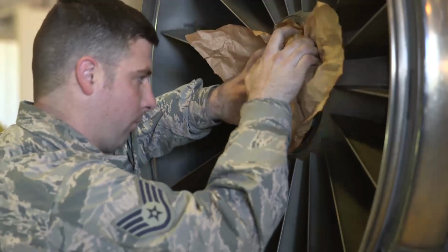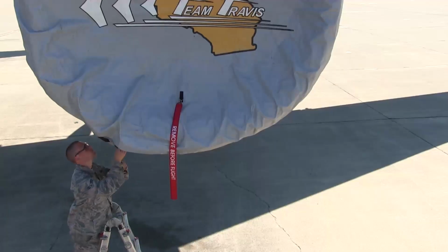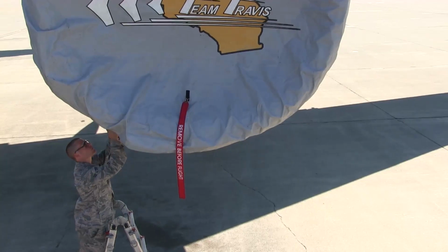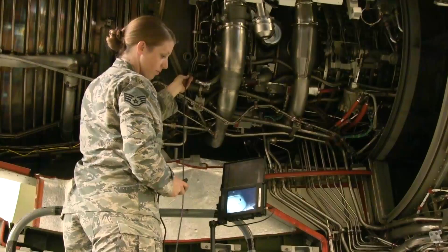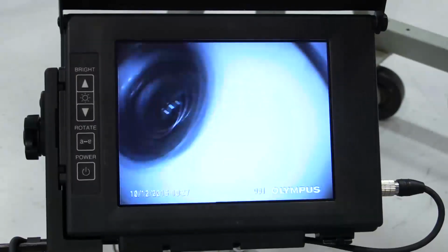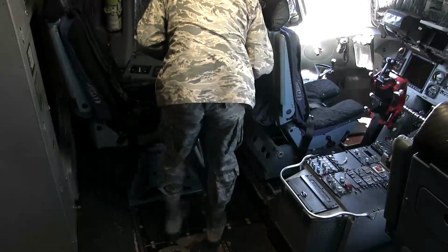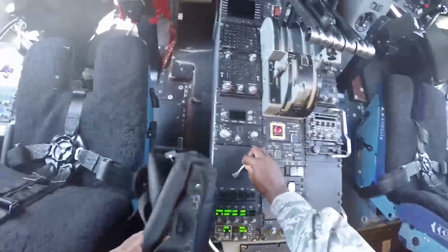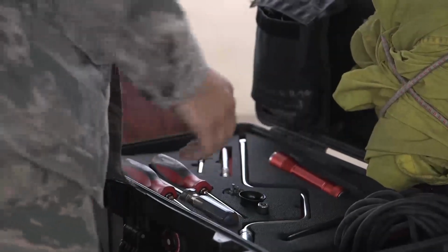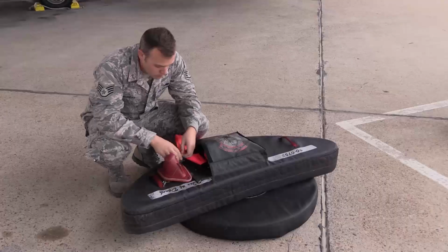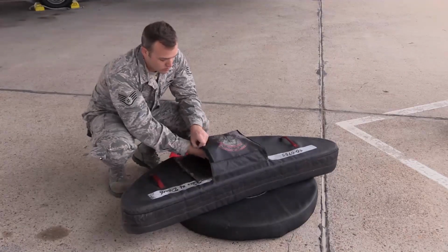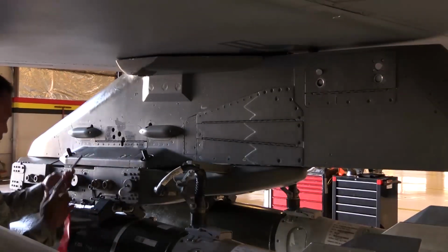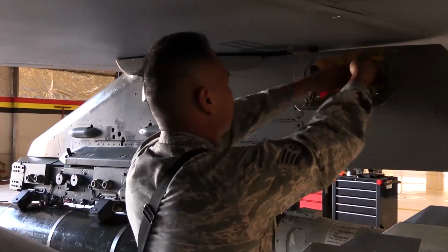Ensure engine run screens and anti-personnel guards are used properly. Install barrier paper, intake plugs, and tape prior to engine intake maintenance. For inaccessible areas, use X-rays, borescopes, or other equipment to locate FOs. Ensure flight deck or crew station FO inspections are completed before and after flight. Account for all tools, rags, and equipment. Account for and secure all -21 equipment. The weapons expediter must account for and secure all weapons-specific safing gear.